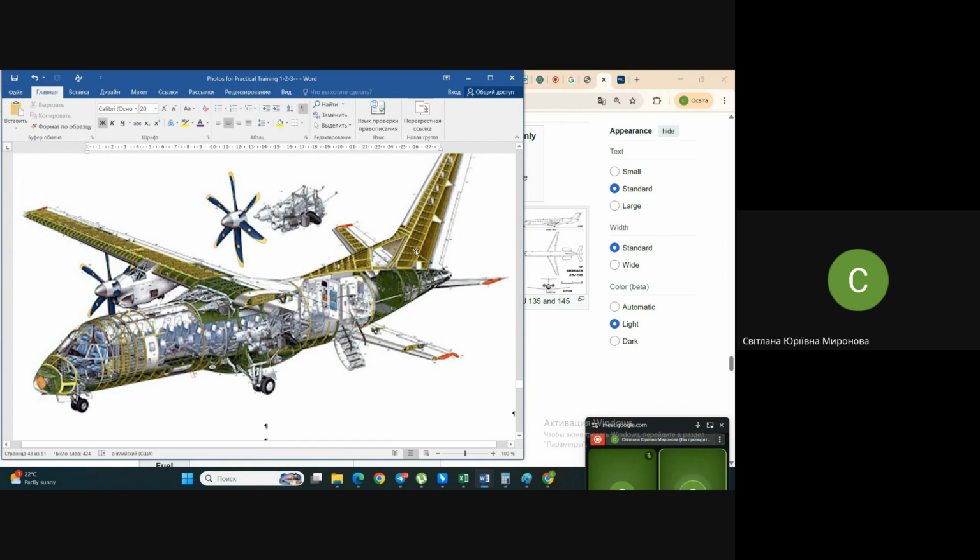To be frank, in real life it's also necessary to calculate their inner volumes, considering their sizes and the relative thicknesses of the profiles that you have selected. And maybe it's necessary to increase the area of the wing in order to increase volume for the fuel, or the area of the fin, or maybe the length of the fuselage.